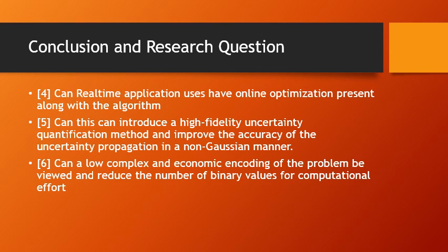This paper proposed three enhancements: a chance constraint MPC navigation formulation, namely an improved binary variables encoding for obstacle avoidance, a piecewise linear approximation of the inverse error function, and a variable horizon formulation.